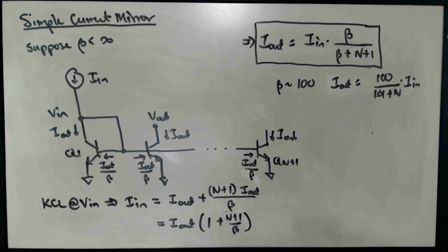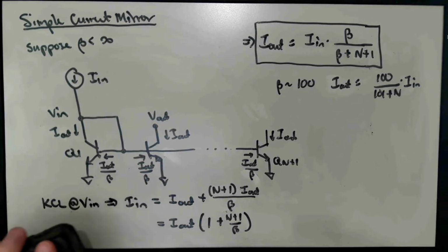And so the number of copies of an input current we can make here with a multiple output current mirror will be limited depending on how accurate we need those copies to be. There's a fairly easy, straightforward way to fix this, and that is to have something else supply the base current.